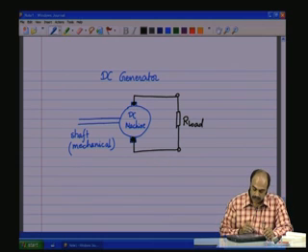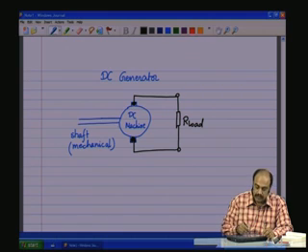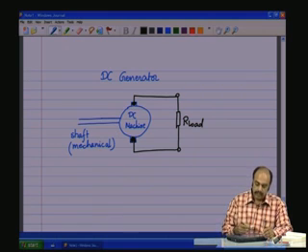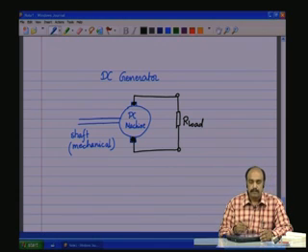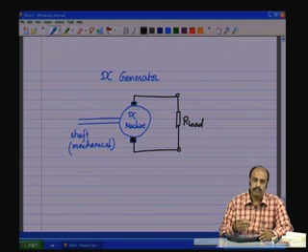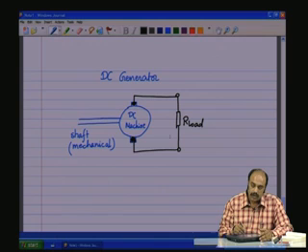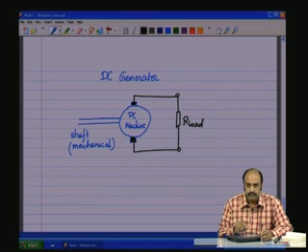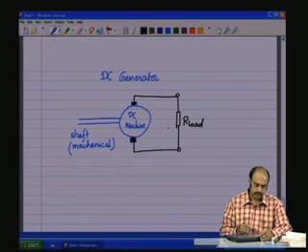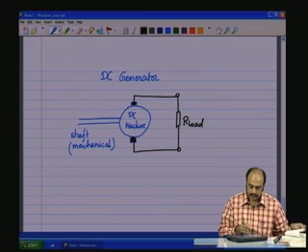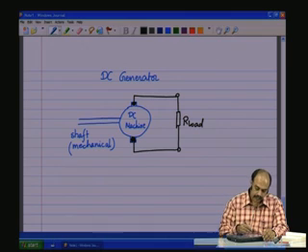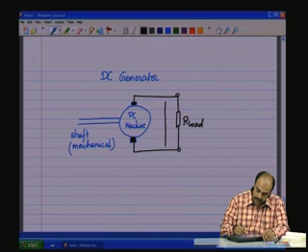So, this is a schematic of the whole DC machine, and we were looking at the internals of the DC machine, how it is structured, and how mechanical rotation can give rise to a voltage, and that to a unidirectional voltage or a DC voltage. So, if we have many slots, many coils per pole, then the induced voltage across the load will be almost ripple free. It will have negligible ripple across the load. And now, let us look at how much voltage is induced across the brushes.